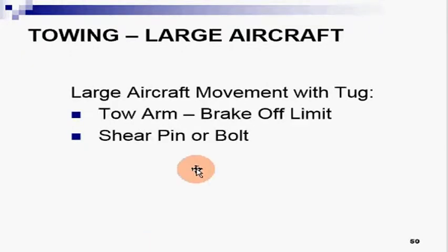Large aircraft movement with a tug: tow arms, break off limit, and shear pin or bolt. Both should be there. There should be a shear pin or bolt installed, and a break off limit. The brake should not be applied before the towing commences.